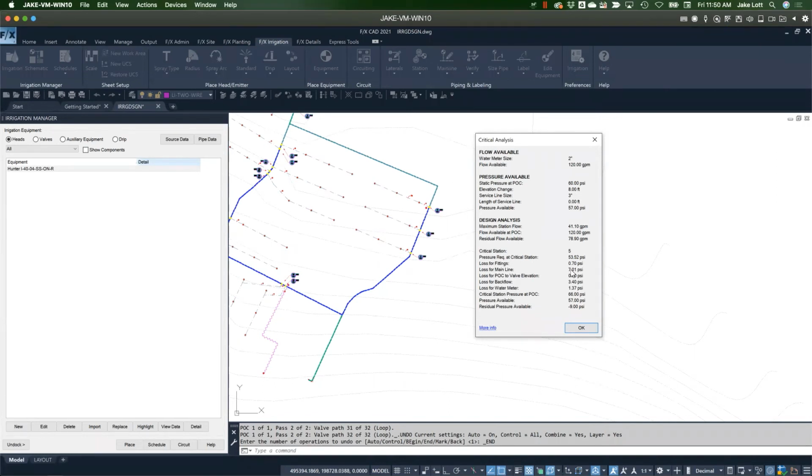Again, one of the factors from a velocity or friction loss standpoint is the length of pipe. We might be trying to take a lot of water and bringing it a really long way. So the longer the pipe segments, the higher the friction loss is going to be. That to me seems actually acceptable. It just looks like what I have available is simply not enough.